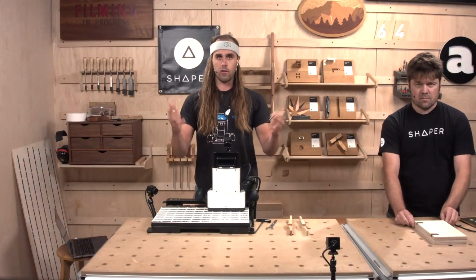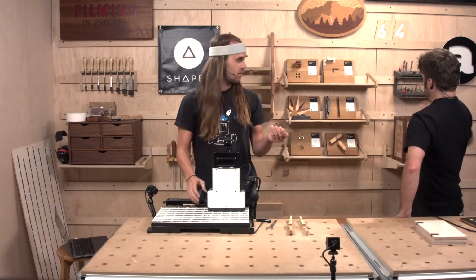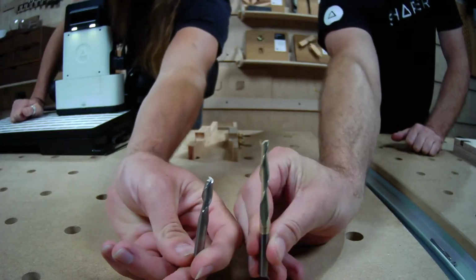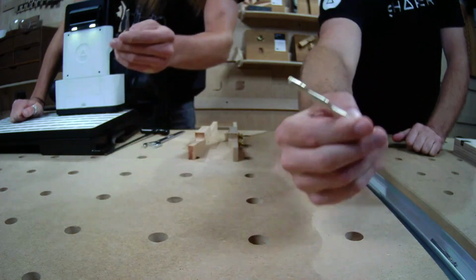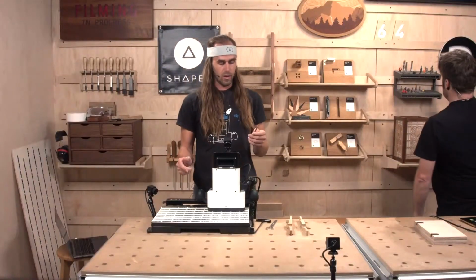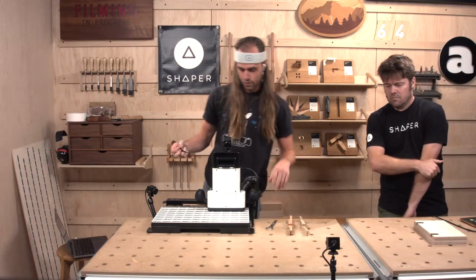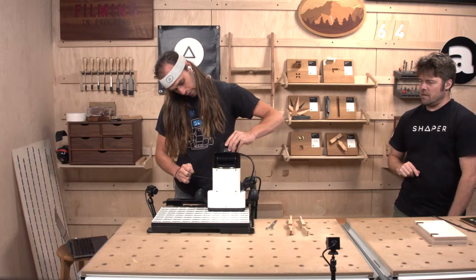So I'm going to show you there's two options. One is you can buy a deeper bit that can cut deeper. Two is you can use these bits. Oh, here's a deeper bit, so we can show you the difference in the length of cut there. This is a 1.5 inch cutter. That's a 3/4 inch. So quite a bit of difference. But I'm going to show you a little pro tip on how to get a little more length out of your cutter while being safe. So if you maybe just get cutting, I'll talk over that as you go. Perfect.